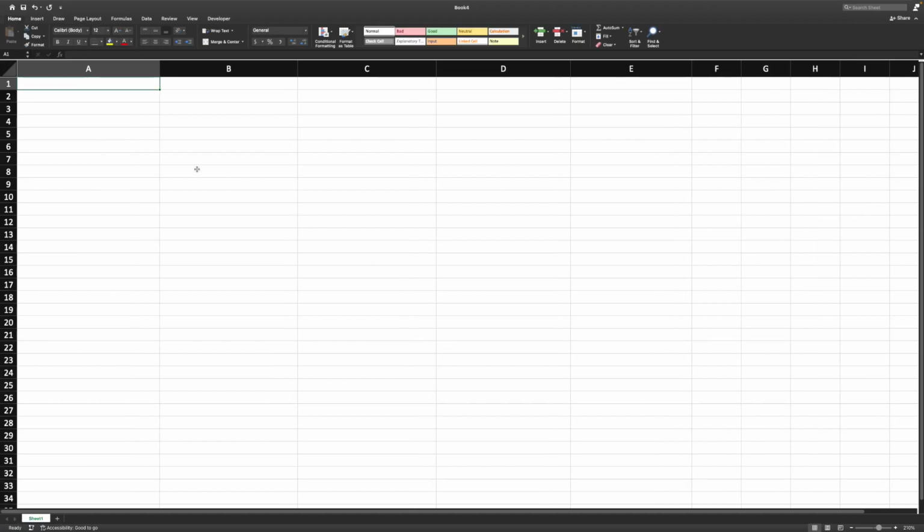Now we open up Excel and create our column headers. The actual name and format of the column headers only matter if we want the add-in to automatically map the columns to each parameter. If the name doesn't match, we can select them manually in the next step. In general, column names should be in the form of object.attribute. The first column sets the name of each new component, so the column header should match our master component name, in this case, box master.